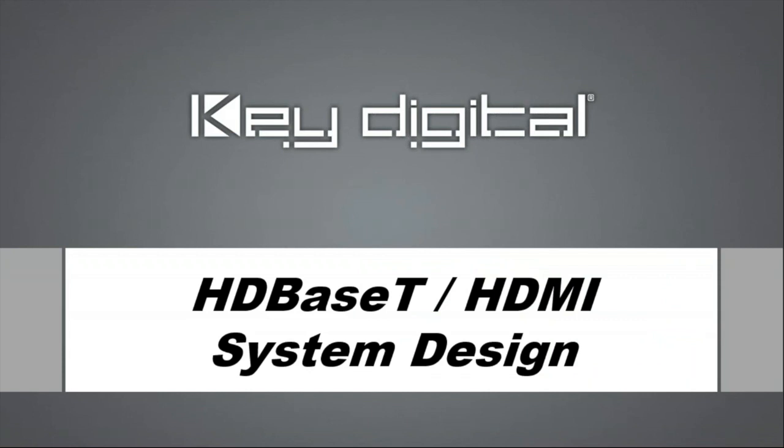We now have the foundational information about the layers of HDMI: EDID, HDCP, TMDS, and what each of those layers does for you. We even painted some pictures of what a problem with each of those may look like. EDID, video but no audio, or maybe a picture that looks neon green, neon pink, or neon purple. That could be from the color spacing aspect of EDID.